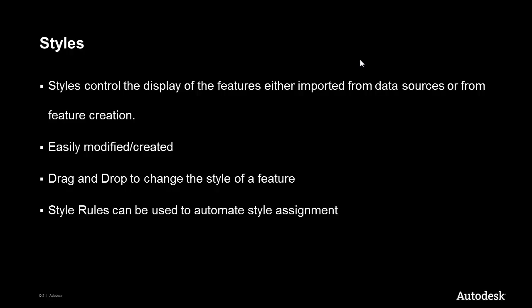So you can actually control the import. I showed you when I picked the roadway styles and the water styles, things like that. You actually have to pick what it's going to look like for the default view, and then you can go and modify later. You can actually modify the styles or add new styles. To change the style, you basically open up the style catalog and you drag on a new one, and it will automatically change it.